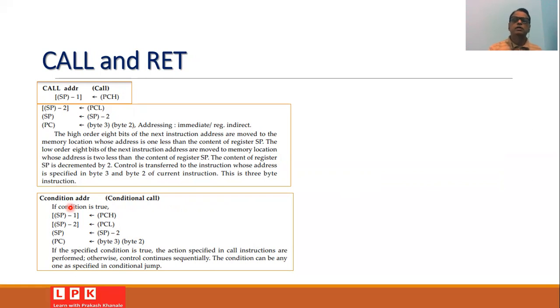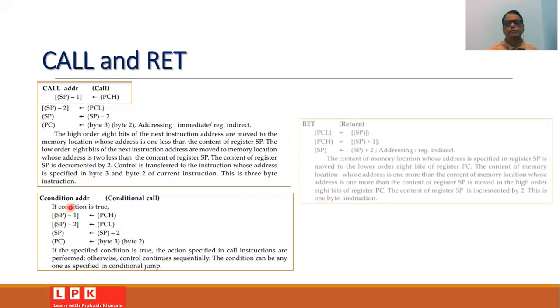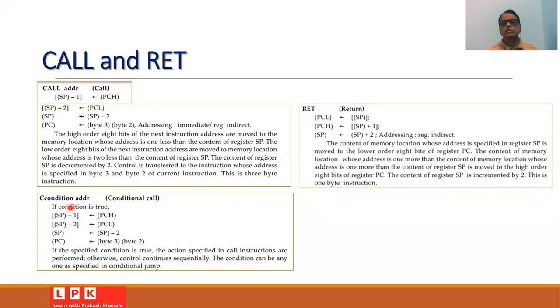So the same conditions, that is zero, not zero, carry, not carry, all such conditions can be used here also in the conditional call instruction. There is another instruction called the return instruction. In the return instruction, the content of the memory location whose address is specified by the register SP, that is the stack pointer, is moved to the lower order 8 bits of the PC.